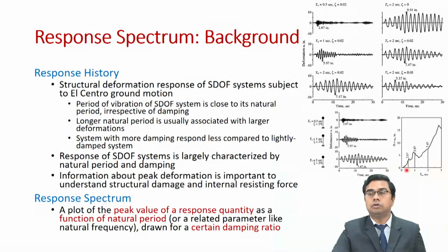natural period, which means on the x axis we have natural period and on the y axis we have the peak values of these structural deformations, the peak absolute value to be precise, and this is provided that all of these single degree of freedom systems have the same damping. So, if we plot them, what we get is the response spectrum for structural deformation.